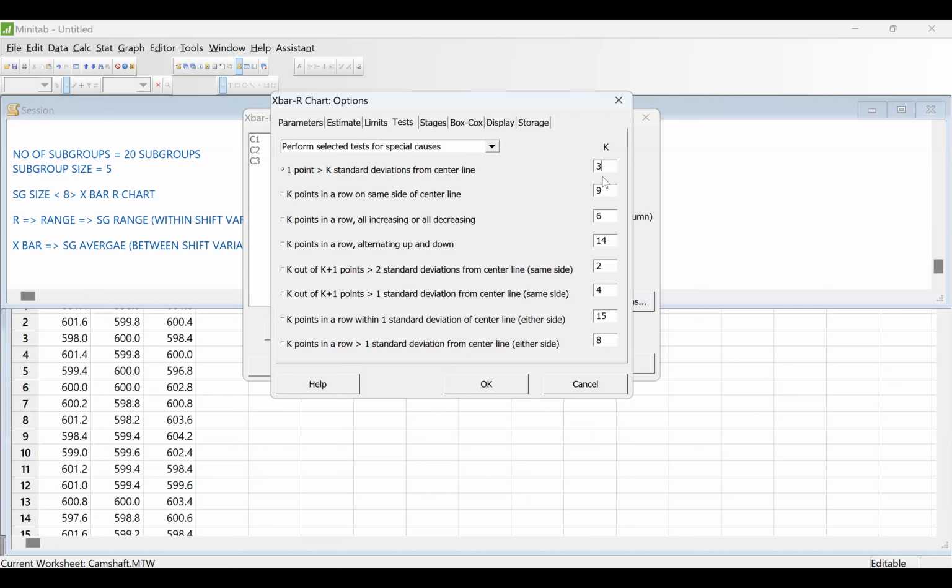Control limit. Upper control limit. If any product is produced outside the control limit, that is clearly an abnormality. Please note, because normal distribution is telling me that there is a 99.73% chance for your items to fall under the control limit. 99.73% is a good chance, isn't it? It's almost like you are winning every time. That is the 99.73. If that itself is not happening, why don't you ask a question?